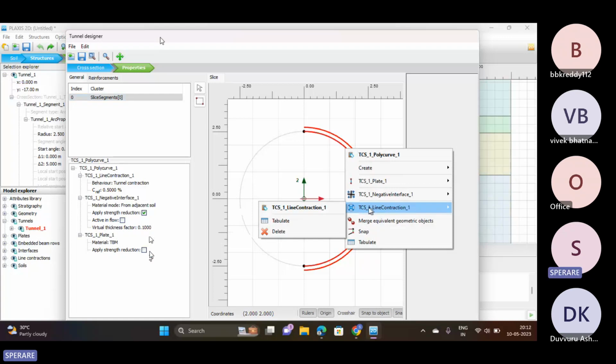For that, we maintain it by changing the cross-section area of the tunnel from the start to the end, and that deviation is 0.5%, an extra pressure that we are going to apply. So the soil will be under some pressure until the lining comes and sits there. This pressure helps you avoid any damage to the soil.